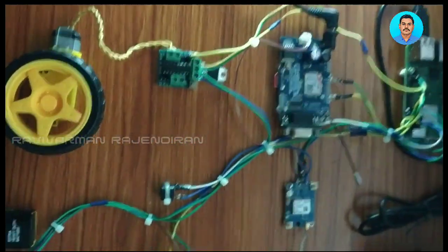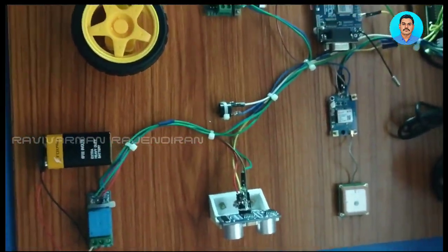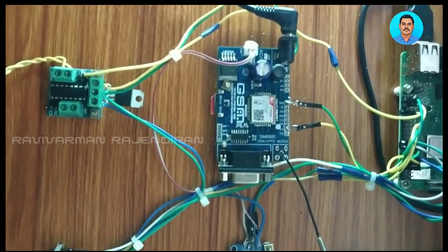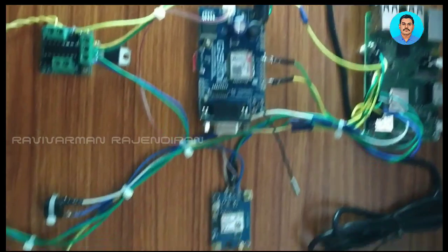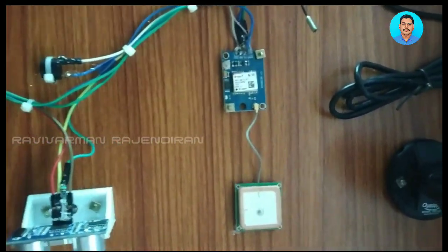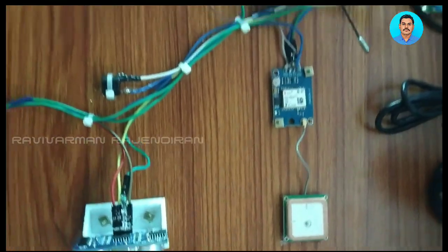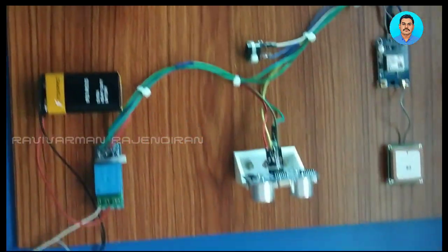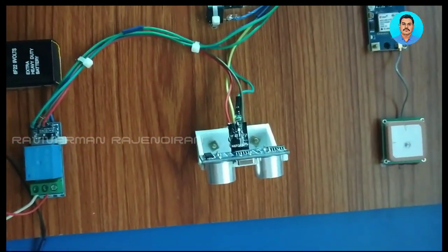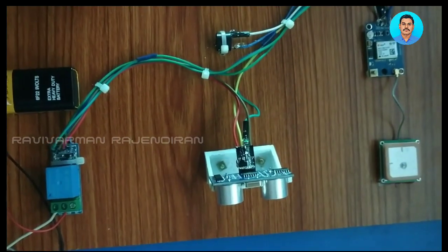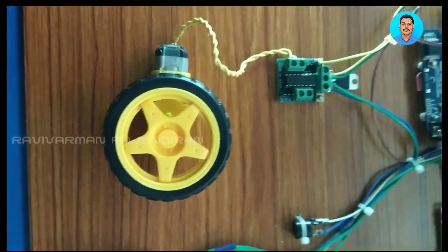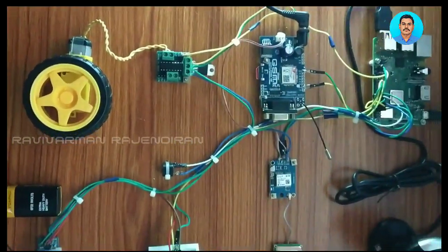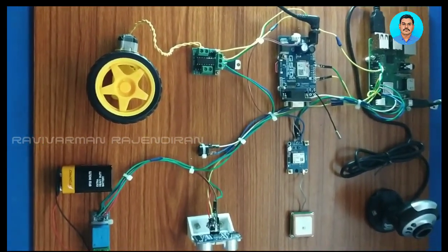And then if even after alerting with the water the driver is not alert, it will automatically send the SMS and mail to the car owner with the location that we got from the GPS device. So this is how the entire system works, and it additionally controls the vehicle based on the ultrasonic value. If there is a vehicle in front of the car, it automatically slows the speed of the vehicle and stops the vehicle gradually. So this is how the entire system works.